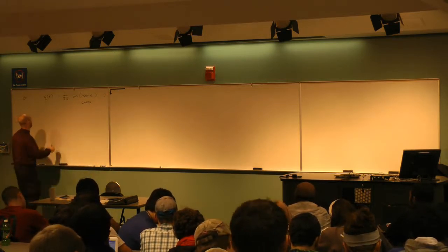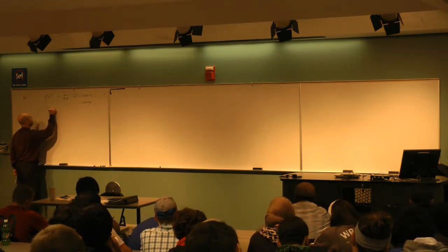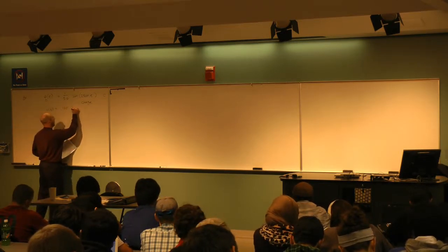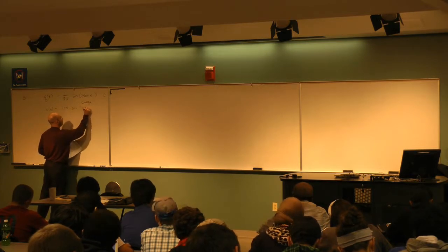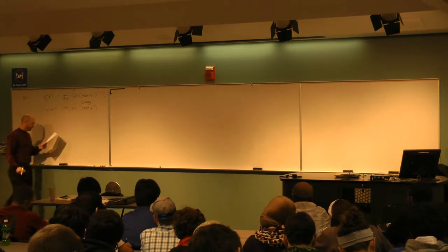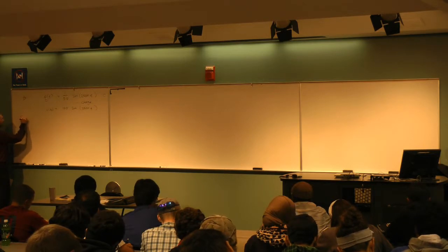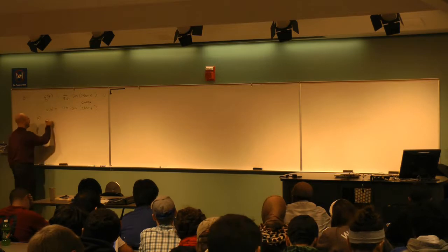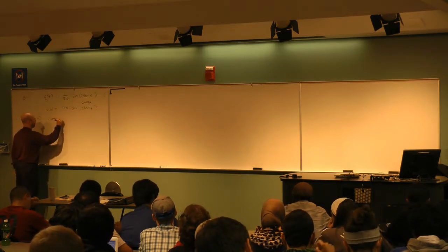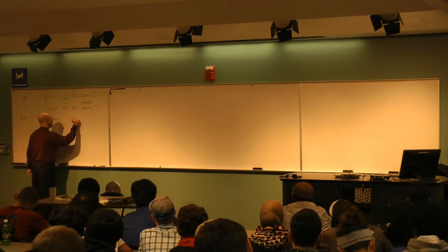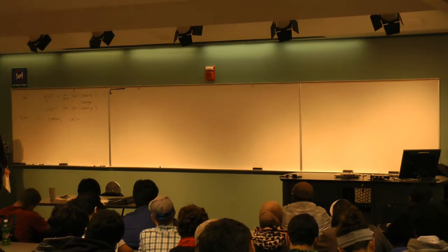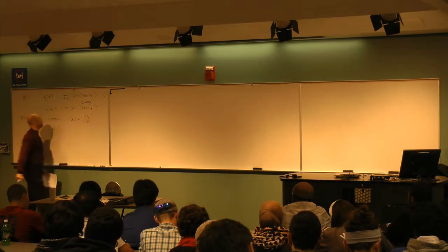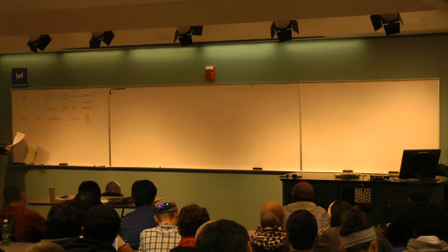Let's say we've got a voltage, V of t, given by 100 times the sine of 250 pi times time, the same frequency. I would like to find a number of different things based on the definitions. So part A, let's calculate the current. The current I of t, by definition the flow of electric charge, is the derivative dq/dt. That's the first thing.